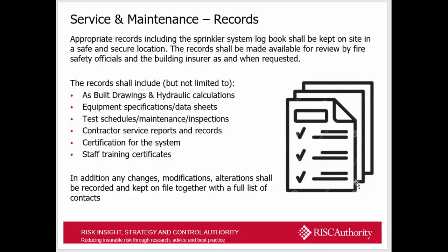the sprinkler system is serviced and maintained in accordance with, one, the standard, whether it be BS EN 12845 or LPC standards, and two, what the frequency of the visits by the contractor is and what is expected of the owner-occupier responsibilities. So it's imperative that these service records are kept and maintained on site, especially the logbook, and the